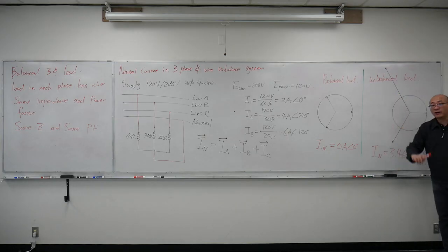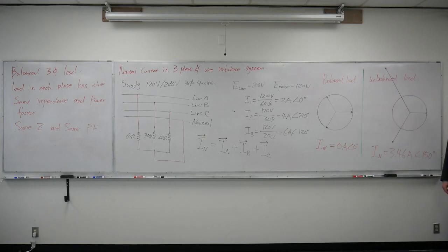But like the sample I gave you, this time we don't have a balanced circuit. So each phase will have a different phase current. We have resistive load, so they're still going to be 120 degrees apart. Now here's my phase A, phase B, phase C. I draw a circle at the shortest one, or the lowest current, which is 2 amps down here.